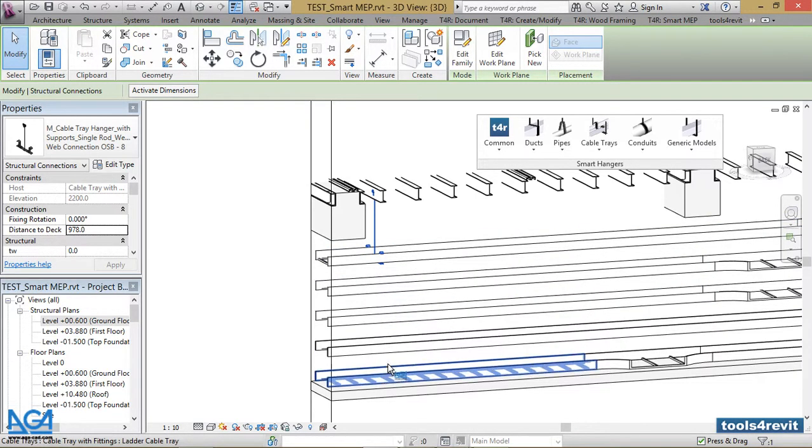You will be just entering the layers, the heights. As I said, Smart Hangers doesn't work with multi-layered hangers because we work with one element only, as Revit just allows to host element only on one particular project.